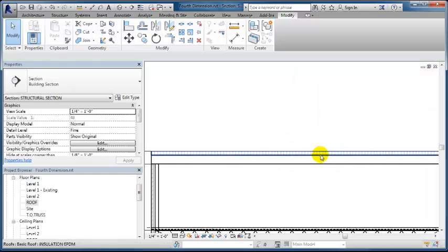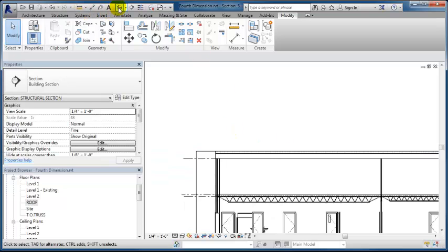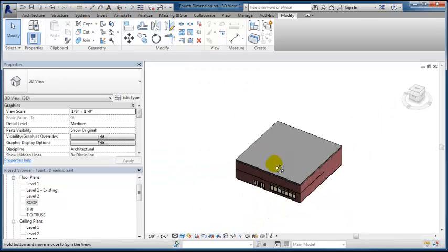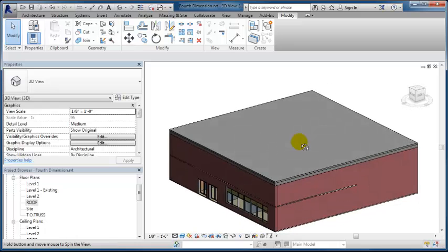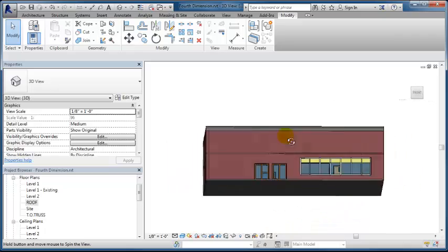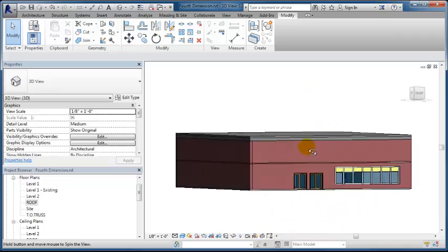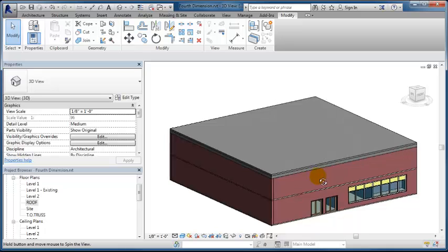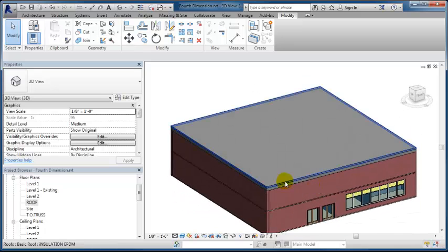And then we can taper it in the middle. So here's where the tapering part comes in, which is really pretty cool. I've obviously got to fix some of this stuff that's sticking out, but you would know how to do that, just edit the boundary. All right, so I want to see here a taper that will be right along where the bearing wall is. So I've got to locate where that bearing wall is. Is that the bearing wall in there? I think it is.